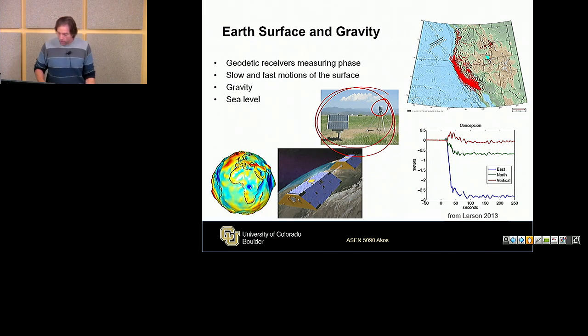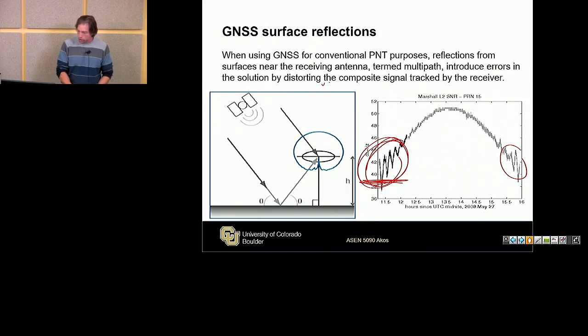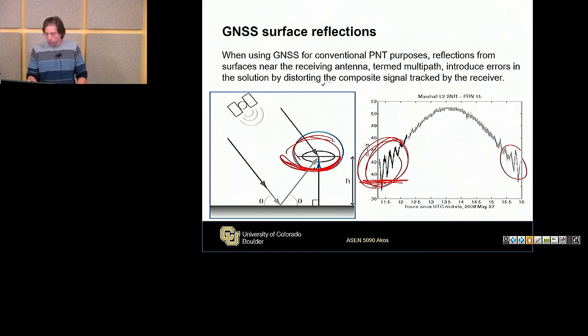That's great. But if I think about this, being an electrical engineer, I'm thinking, well, this antenna is really designed to reject all these LHCP signals from this path, as well as all these LHCP signals from this path. And these antennas are $2,000. So what we did is I said, if I just use a simple cell phone antenna, which is on the order of 10 cents. My cell phone antenna doesn't know what direction the signals are coming from, and I don't really put the polarization in there because I want to get any signal energy I can. So a cell phone antenna, which is usually linearly polarized, gets a signal from all locations as well as a reflection, so it's much more receptive to this reflection coming off the ground.